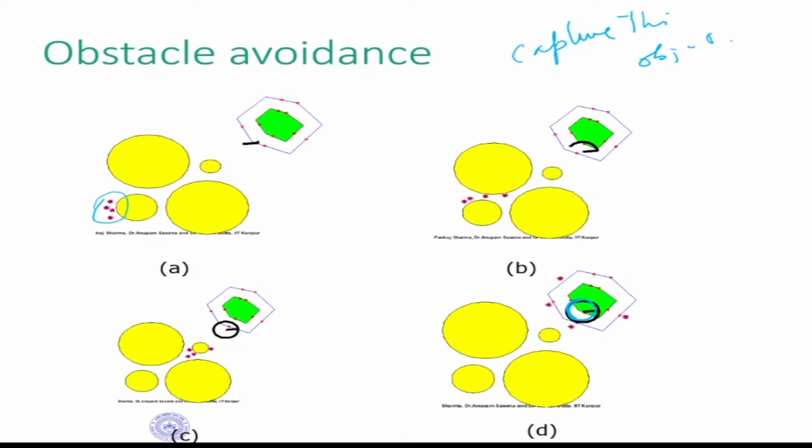So the first thing it has to do, it has to find out on the expanded boundary where it will go and sit first, then where it will go and catch the object by using what we just discussed, optimization. So from the optimization, the answer would be that the robots need to go and sit on the boundary first, here, here, here, and here. And then on the object itself, these are the points where the robot should go and sit, to satisfy form closure. Then it is caught. So this is the first.